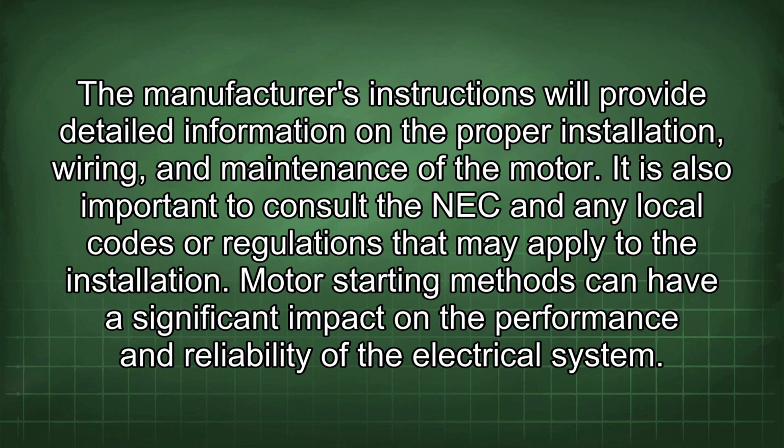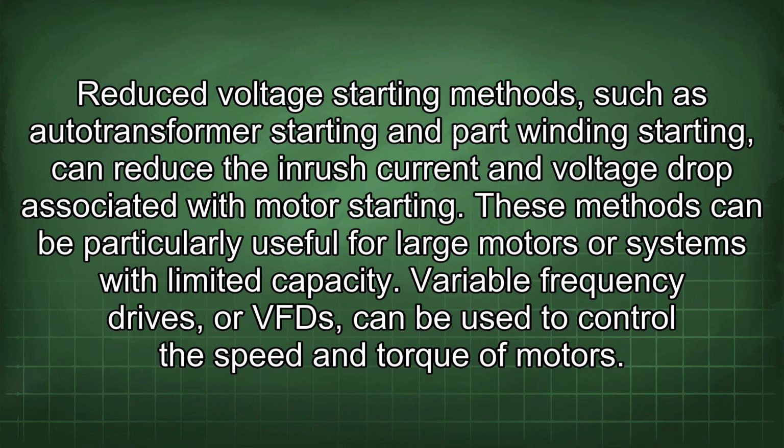Motor starting methods can have a significant impact on the performance and reliability of the electrical system. Reduced voltage starting methods, such as autotransformer starting and part winding starting, can reduce the inrush current and voltage drop associated with motor starting. These methods can be particularly useful for large motors or systems with limited capacity.